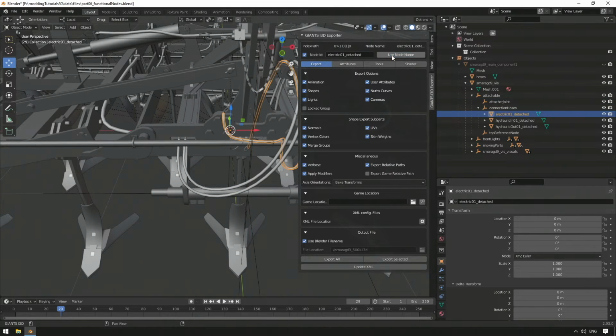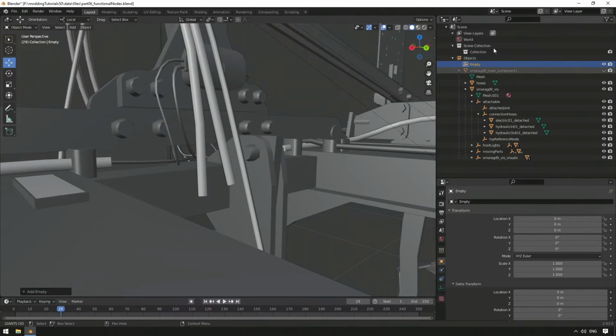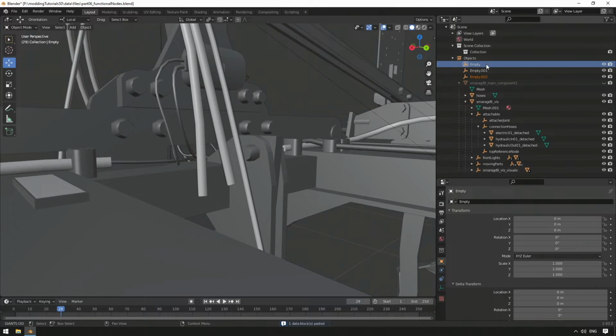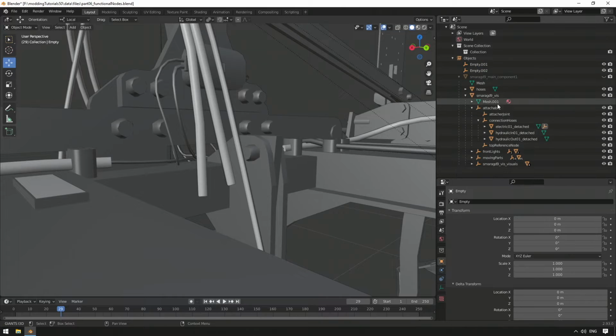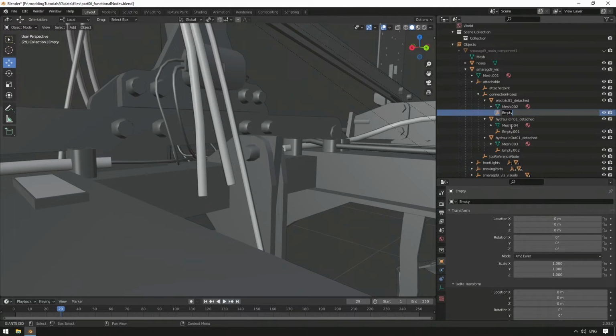Thanks to the possible shared objects that are in the base game, we can load unified models of connectors from our game folder. Here we need to set transform groups that we can reference later in the XML with i3D mapping. We have to rotate them on the x-axis so the direction will fit later. We choose the names electric_01_detached_adapter, hydraulic_out_01_detached_adapter, and hydraulic_in_01_detached_adapter.